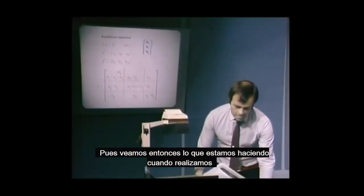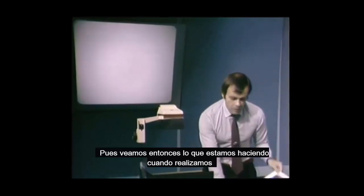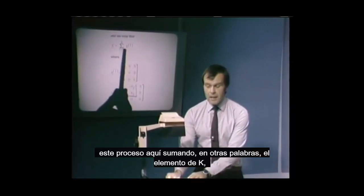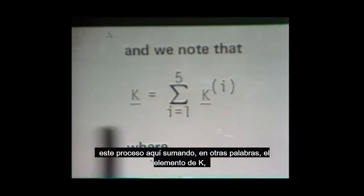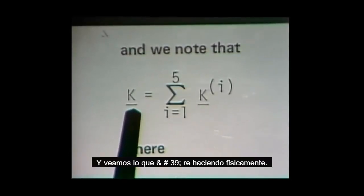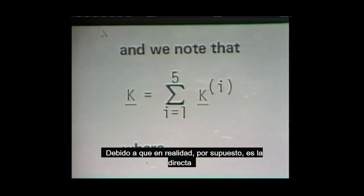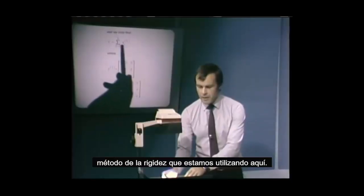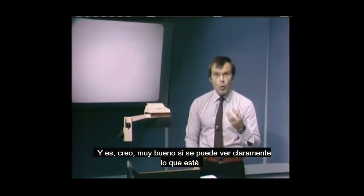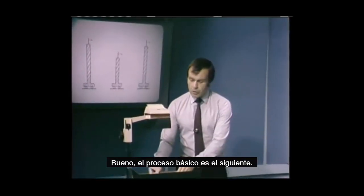Let us look then at what we are doing when we perform this process by summing the stiffnesses of the elements into a global stiffness matrix. Let us look at what we are doing physically, because that really is the direct stiffness method that we're using here, and it is very nice if you can clearly see what is happening in that method.